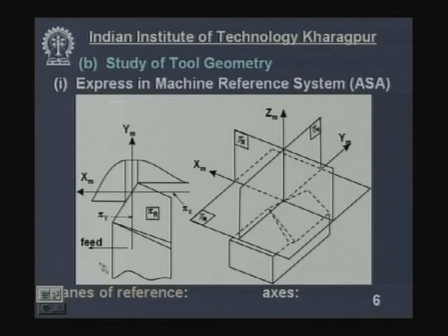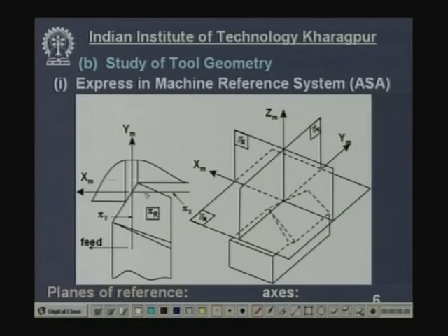so in this diagram this shows the turning, the top view of turning operation and this is the horizontal plane, okay, and you take any point on the cutting edge, and since it is horizontal plane, velocity vector will be perpendicular to this plane.